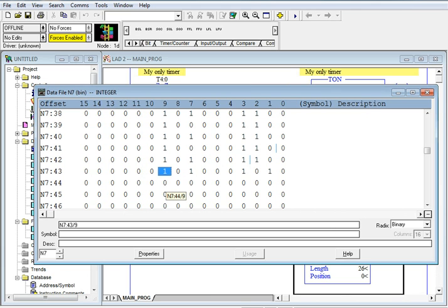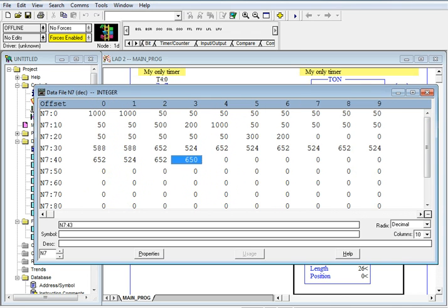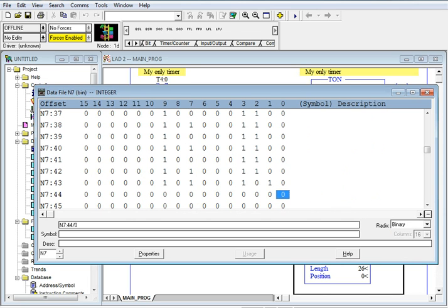Now I'm at 44. Now 44 should be timer 24, and we're going to come back up here and look at timer 24. 24 is the 10 seconds of walk. Okay, we're ready to do the 10 seconds of walk. So I'm going to go back to binary. I'm walking the other way, so the 8 guy will be 1. I'm still don't walk here, but my lights have changed.